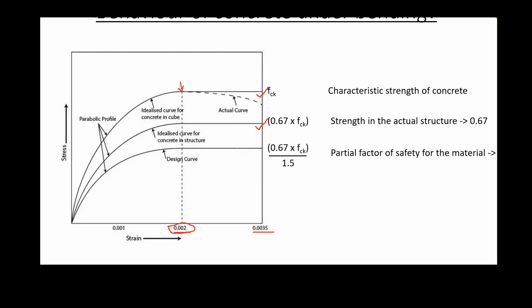This is the peak. Then why 0.0035? When a strain of 0.0035 is attained in the beam of any grade, we can see visible cracks developing. This indicates a kind of warning to the occupants. So that's the idea behind that. So we have seen these two cases now.